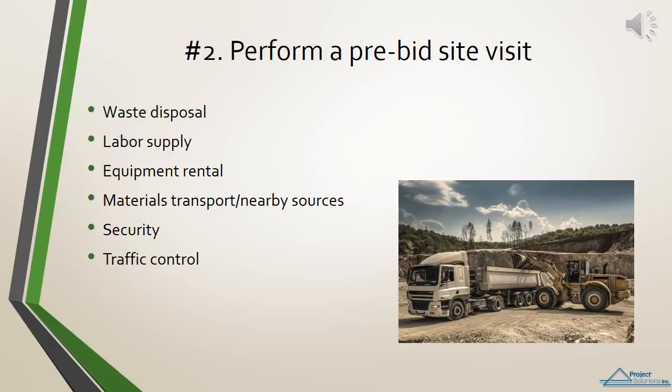Is equipment rental available, and how near is it? How far will contractors and suppliers need to transport materials? Are there nearby sources of concrete and lumber? What security measures will be needed for this site? Will you need traffic control and/or flagmen?